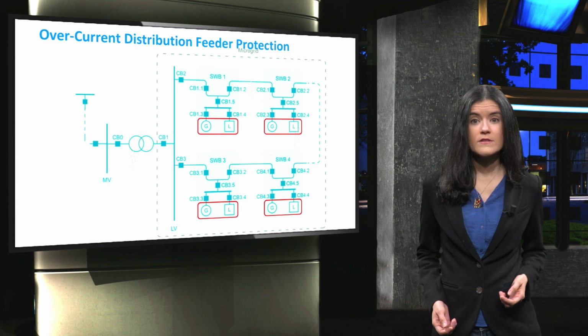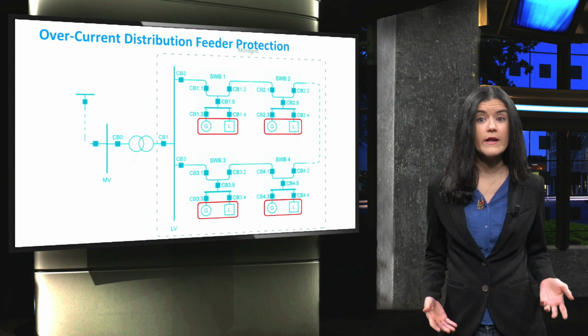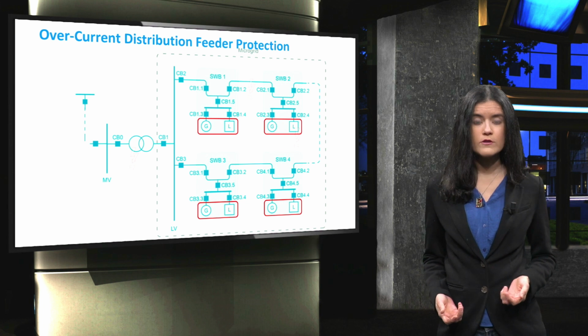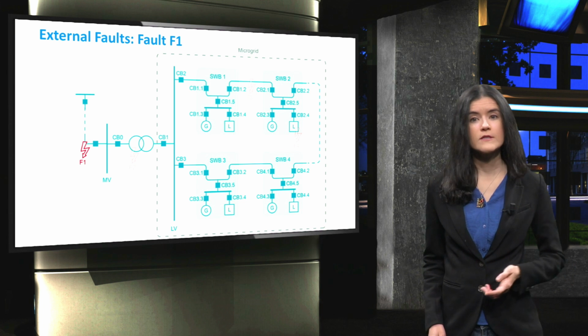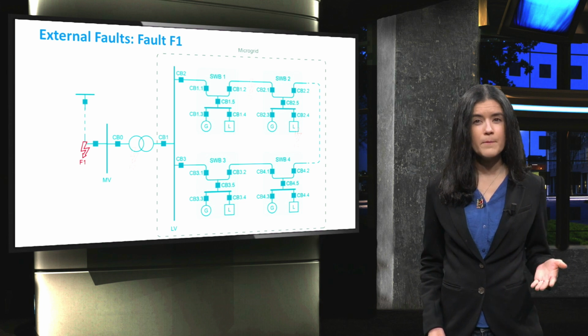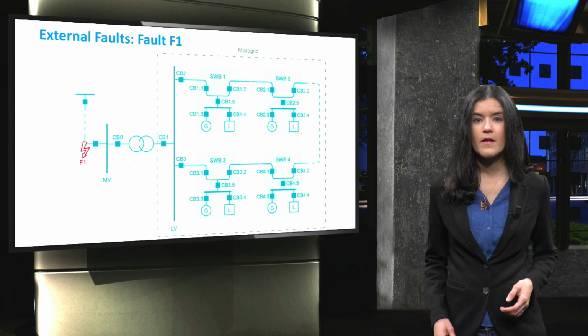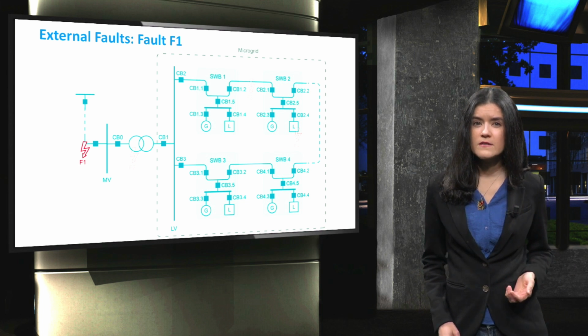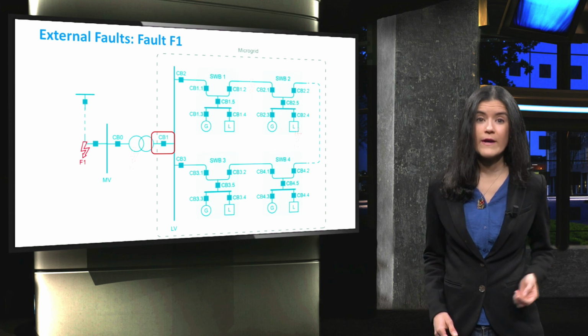The circuit breakers are responsible for tripping and isolating the different areas, distributed generators, loads, and/or feeders during a fault. When fault F1 occurs, that is on the medium voltage feeder towards the grid side, then the microgrid is isolated as fast as 70 milliseconds. The challenging part of this case study is that the amount of fault current at CB1 can vary greatly.